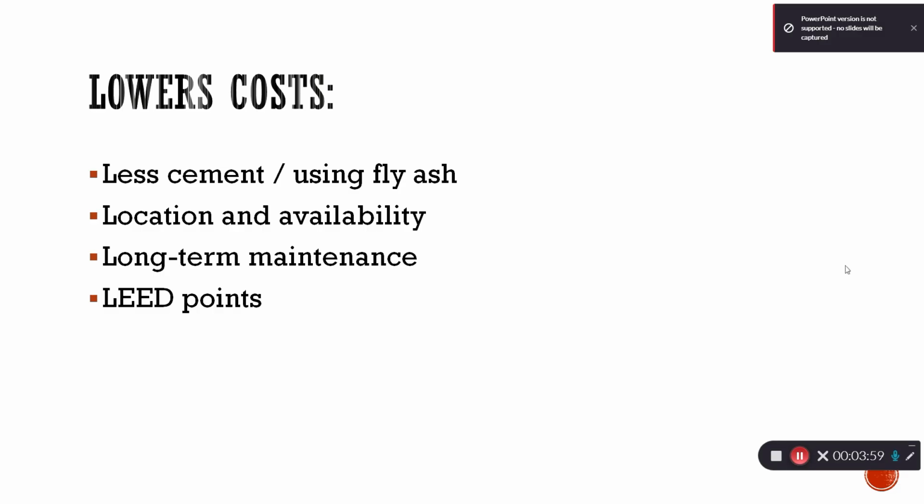Fly ash has less long-term maintenance than Portland cement. The concrete produced from geopolymer binders like fly ash is sustainable and can have unparalleled engineering properties. This contributes to the improvement of development and sustainability in construction practices. So because of this, fly ash has the benefits of unparalleled engineering properties such as improved workability, durability, and resistance to certain chemical attacks. Fly ash has less long-term maintenance than regular Portland cement does. This helps to lower the cost of fly ash throughout the lifetime of the concrete the fly ash was mixed into.